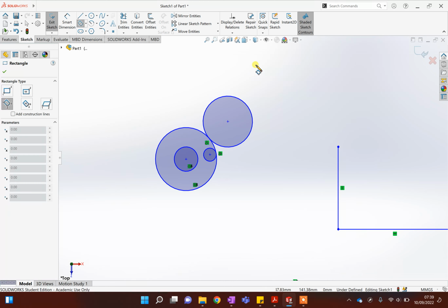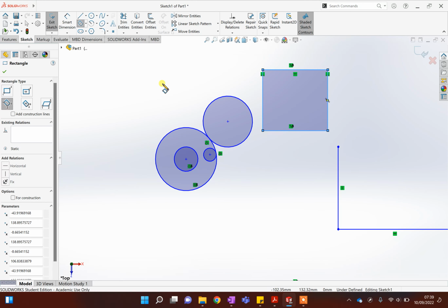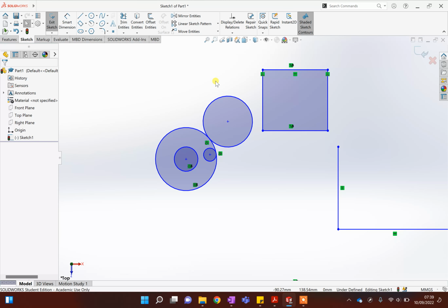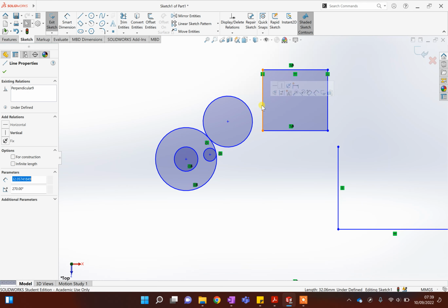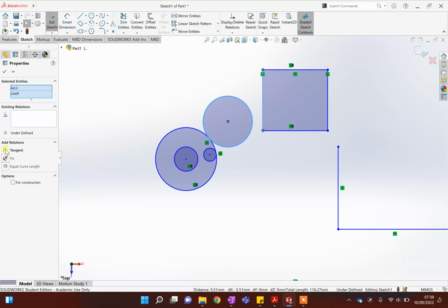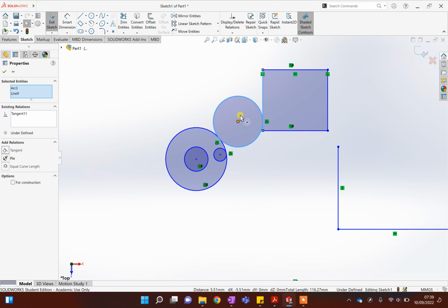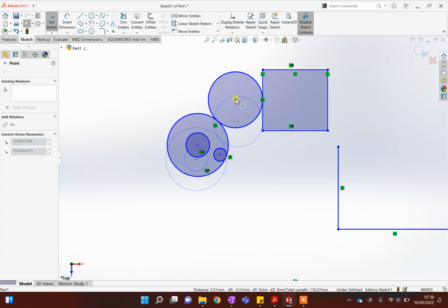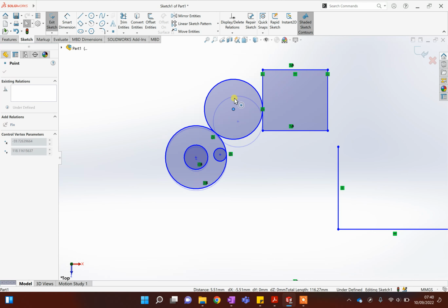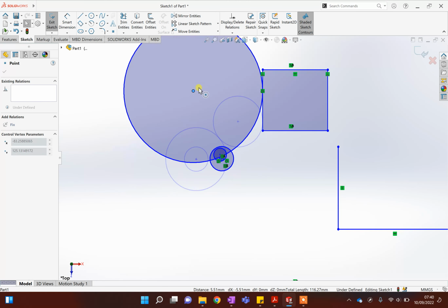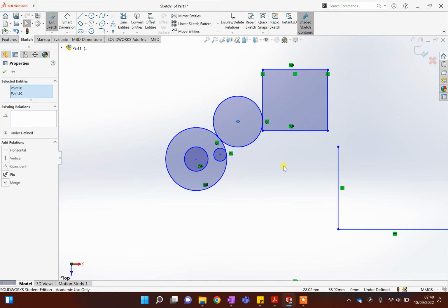Maybe you've got a box, just drawing a box, and you want the circle to be stuck to the edge of the box, you can pick one edge of the square, hold Control, pick the circle, and choose a tangent as well. There we go. And now that circle is bound to that edge of the box. You can see it. All right, really, really useful. So play around with all the constraint tools. Sometimes you want to get rid of them because they're annoying.